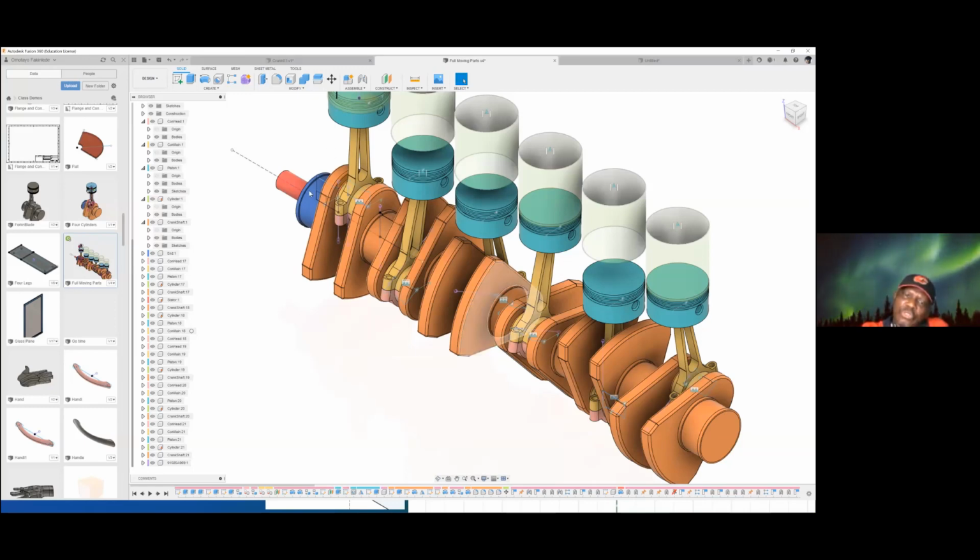So what I want you to do is to do the individual connecting rods, do the individual sections of the crankshaft and be able to rotate them at will. But don't do the rotation yet, because it is usually much more efficient to do everything when you have gotten a complete assembly. Because if you do a complete assembly, all the rotation will take place, including the position of the piston, so of the connecting rod.